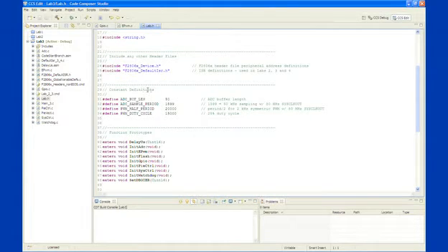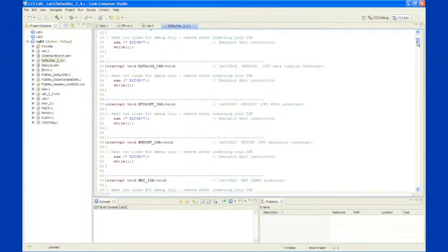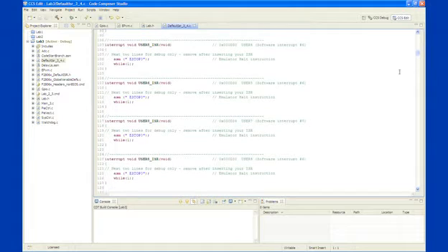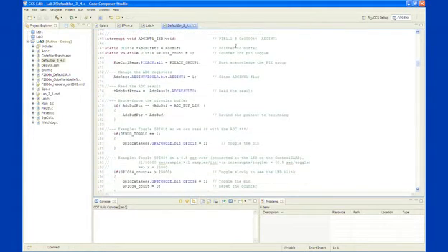One other thing we want to take a look at is the ADC, which, as we know, is going to be sampling the PWM waveform. Inside of the ISR, located right here at 1.1, we're setting up a circular buffer, and we're going to plot the circular buffer out with Code Composer Studio.